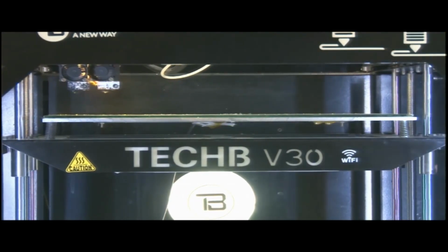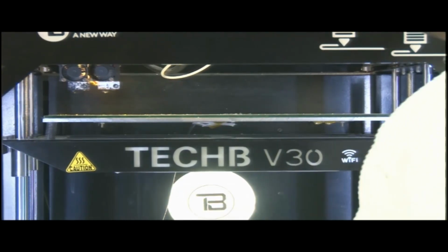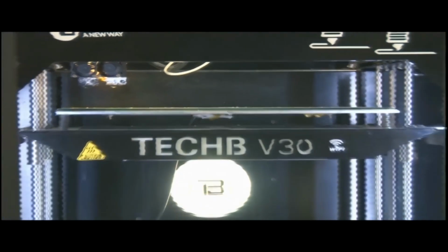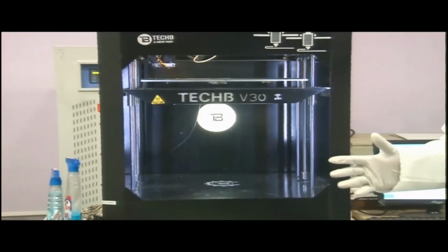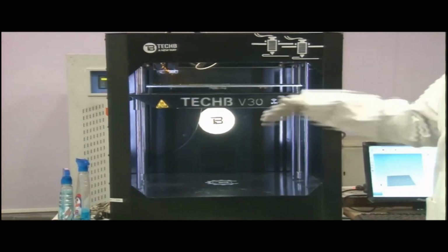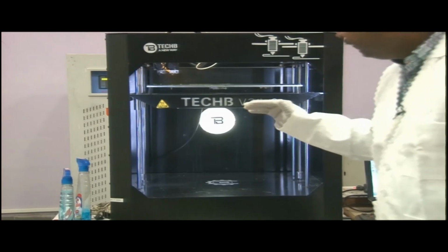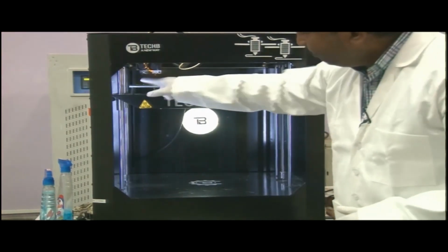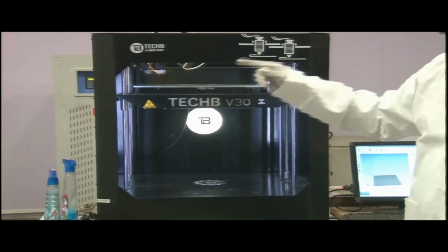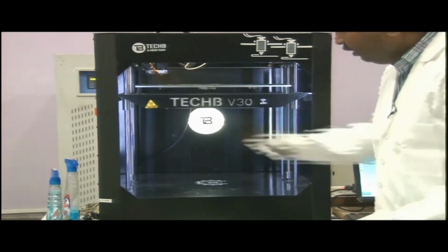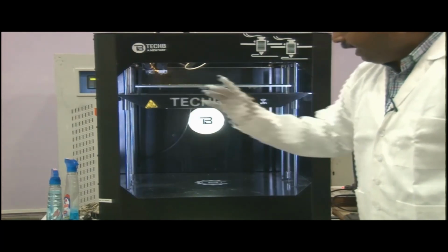In this software we can set the layer thickness in slicing to 0.1, 0.15 or 0.2, the 3 levels here. Whenever we change this layer height parameter, we need to maintain the gap as well. Say I have fixed 0.15 from the top of the bed to the tip of the nozzle. We need to set this gap and lock the limit switch.